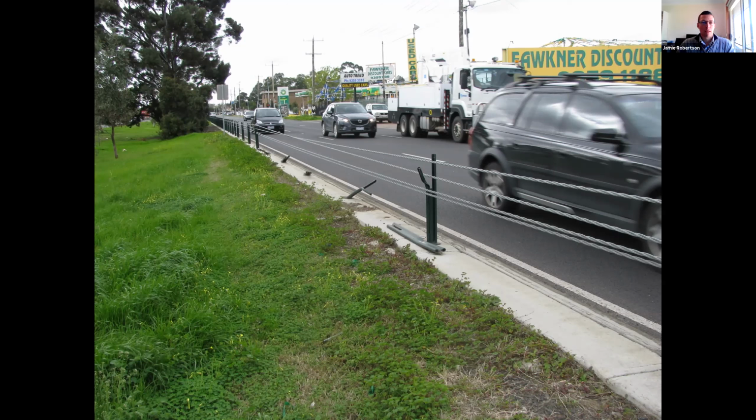This barrier here obviously is at a very minimal offset of perhaps a few hundred mil. It's on Sydney Road in Melbourne and it keeps being struck. It's a real maintenance burden, this one. It is a wire rope, so every time it is struck, it needs to be attended to. So perhaps the choice of system here wasn't the best. There's not much scope perhaps to have installed that barrier further from the road due to trees and other hazards. Maybe there was, but if that could have been located a bit further away, and perhaps if we went with a more rigid system, due to the reduced deflection, that would have been a better outcome.